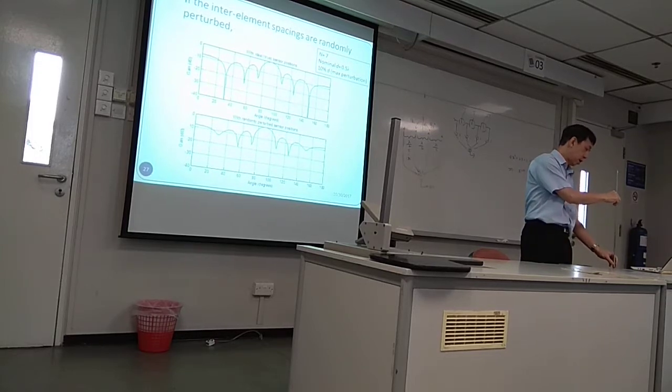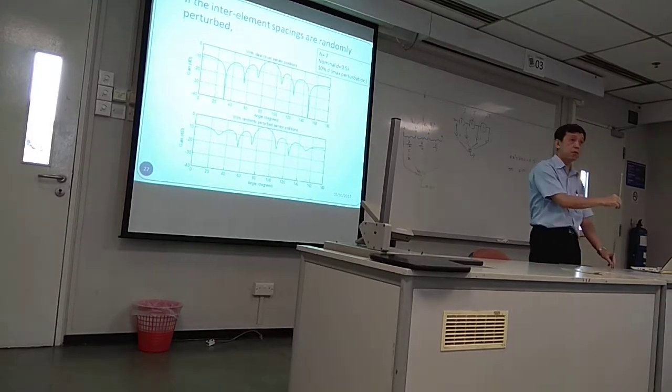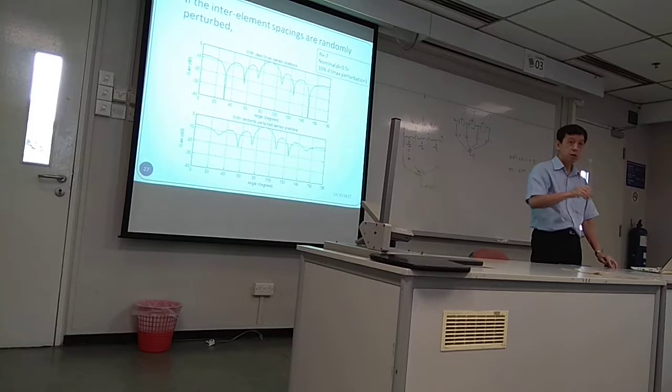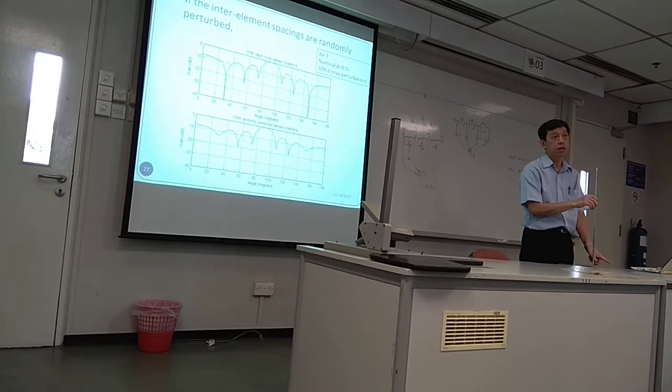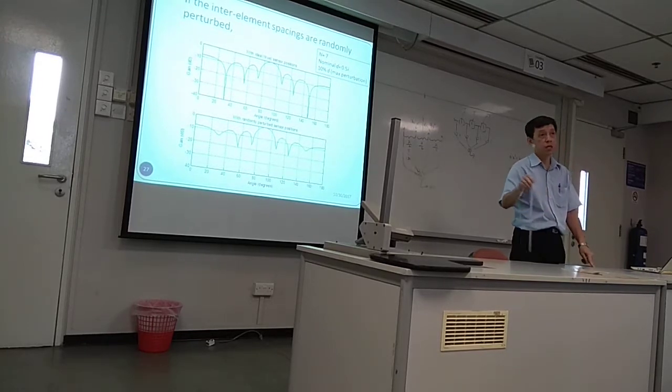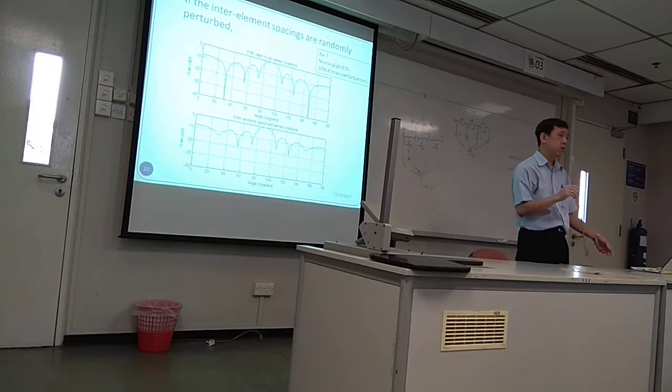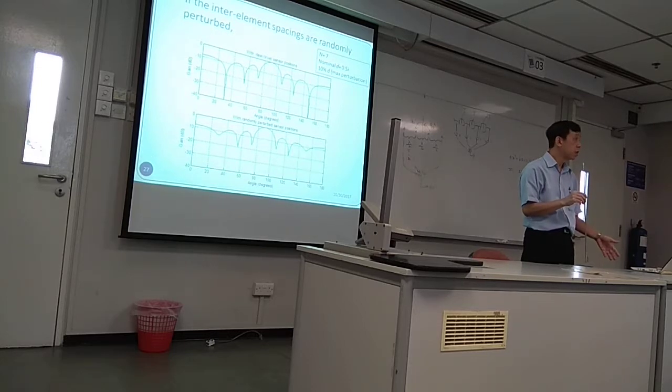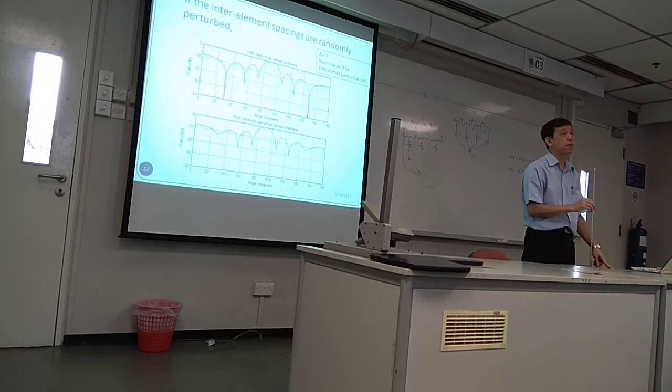So now, I have a linear array. I need to mount the monopole antenna along a straight line, right? One here, next element here. You say, okay, half wavelength, right? So we can actually mark up the position and then mount the antenna accordingly. But this mounting is going to give you error. So supposedly the half wavelength may be, say, 1 meter. The mounting may be occurring at a distance 1.01 meter.